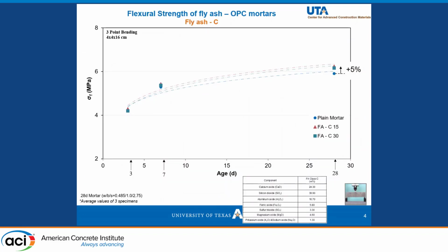First, we evaluated the flexural strength of mortars with fly ash type C at 15 and 30% cement replacement.